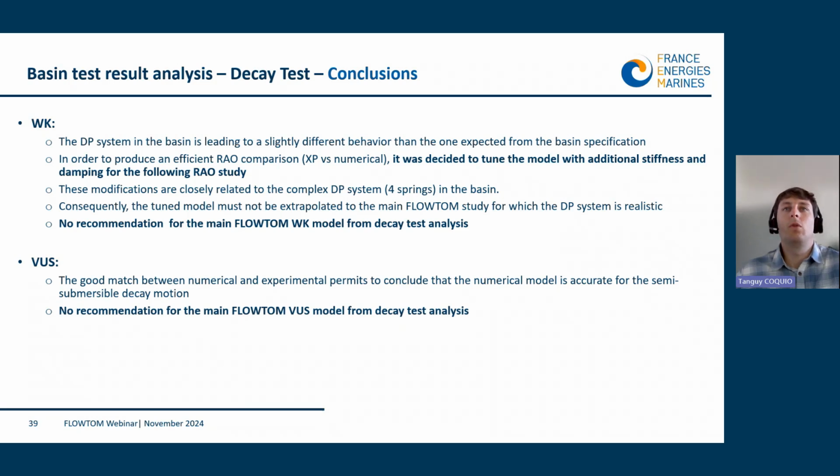So we decided to tune the model of the basin, with additional stiffness and damping, for the following RAO study. But this tuning is really dedicated to the basin model, meaning it is to take into account the spring and various elements in the basin, for example the spring, but is not necessary for the main FLOWTOM analysis, as we are not considering the spring in the main FLOWTOM analysis, but an equivalent dynamic positioning stiffness matrix with additional damping.